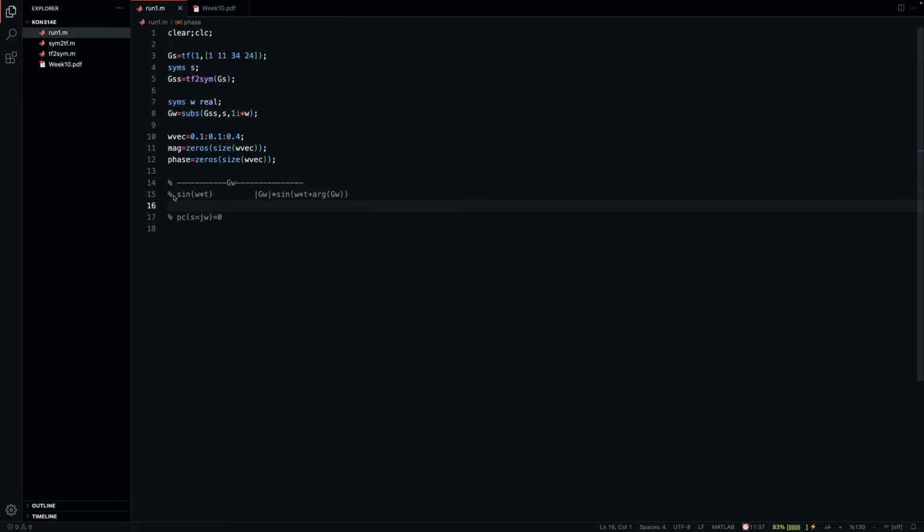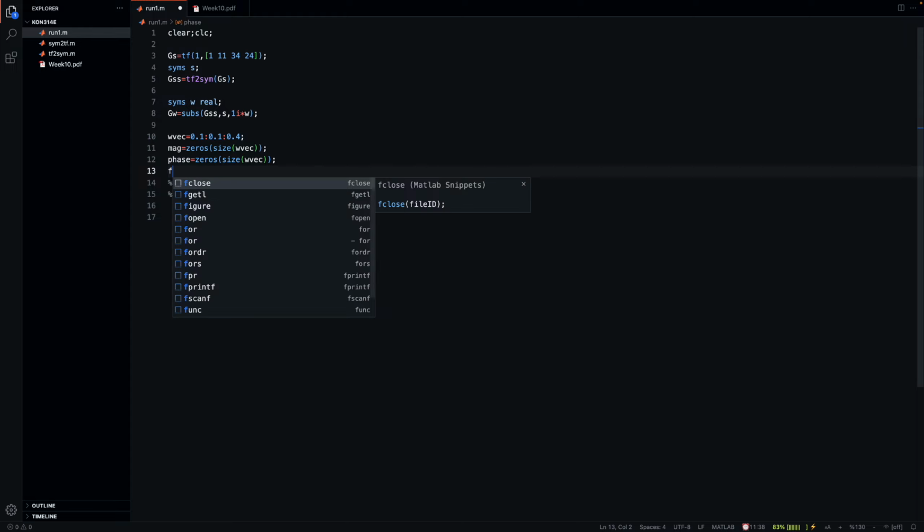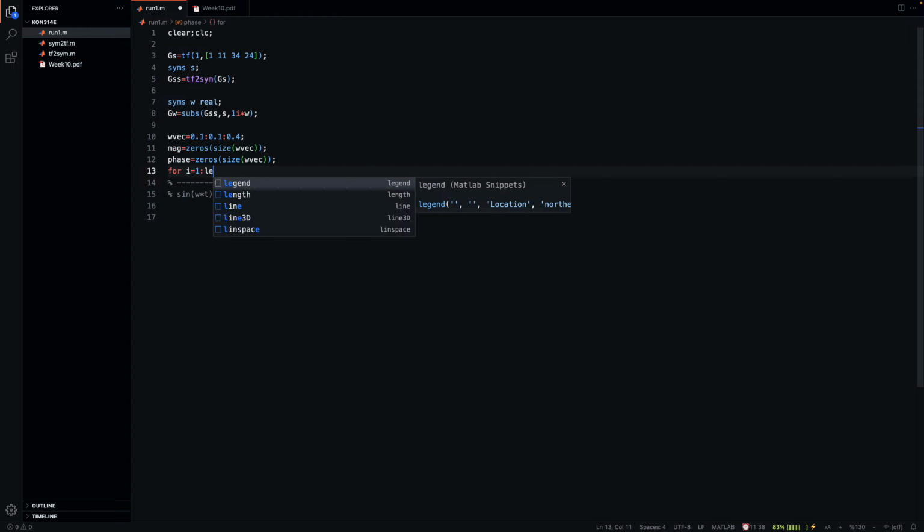So unit amplitude, g omega, will be the amplitude at that specific frequency. So we're working with a specific frequency, omega star. And again, at that frequency, we will have basically a phase angle. And that's basically it. So let's see how this looks, because we will plot this. And the common axis is going to be omega. Therefore, let's actually open up a for loop here.